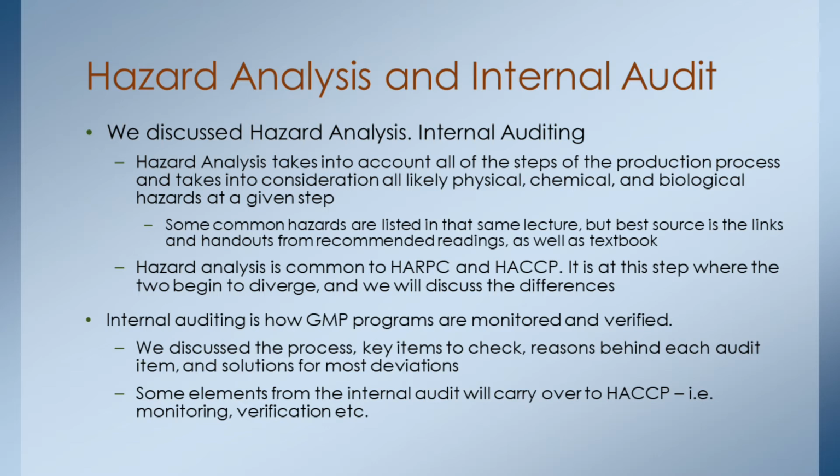For example, let's say you're doing a pasteurization process, like you're working for a milk company. Well, you got that milk pasteurized, right, in order to protect it from bacteria. What specific problems arise when the pasteurization step is not done properly? Well, if pasteurization isn't done properly, you run the risk of E. coli, salmonella, even listeria. Those often have to be taken into account. And you would know that they're biological hazards, so what can you do to stop them? Well, you need to check to make sure that it's cooked at the proper temperature and for the pre-designated amount of time that your team was able to prove was valid for destroying the bacteria that are in the milk.